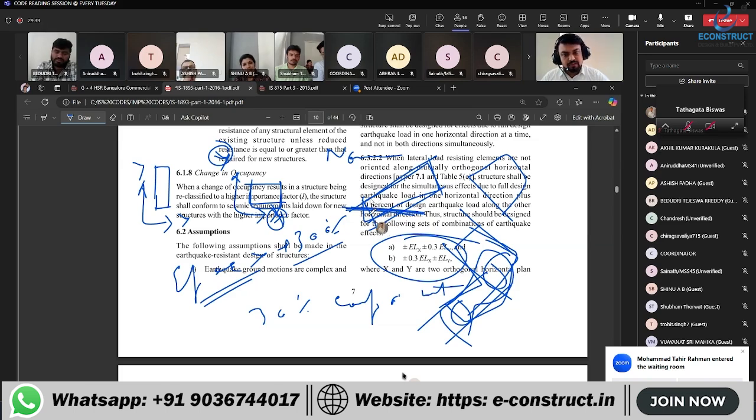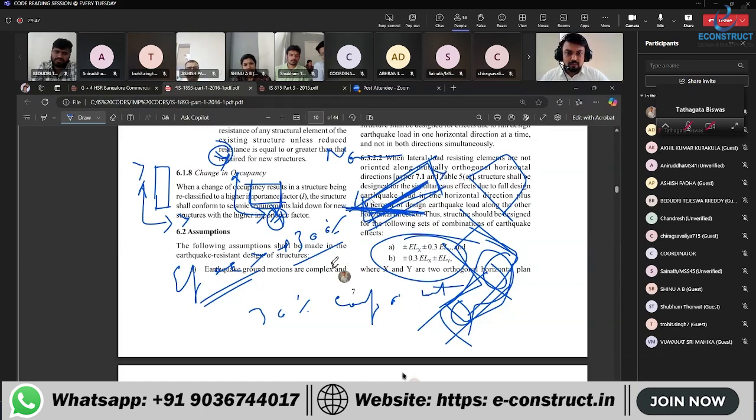On the basis of this there will be a local axis and a global axis. On the basis of the local axis, the x force will be applied. But what about y? There would be a certain component in y also for this particular column, because it's not straight, it's inclined. So that component we take as 30% of the actual y forces.